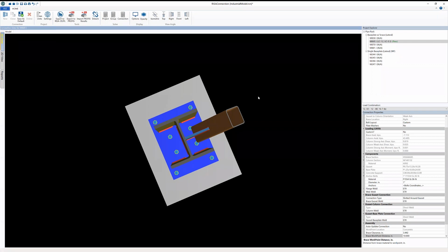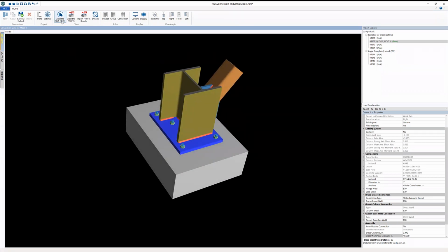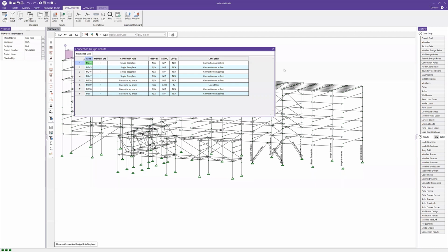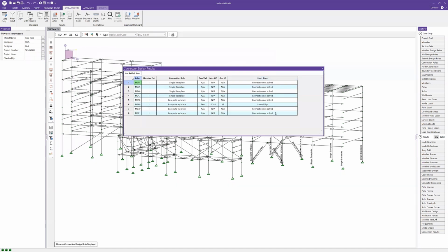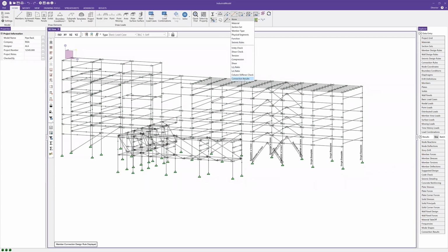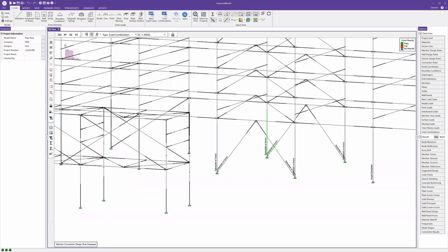With that, we can bring this model back into RISA 3D. Also, just to mention, this is one of the things that was new to the version earlier this year. We do have the ability to export to Profis, so you can connect with Hilti Profis to do the anchorage design, the concrete to anchor bolt design for all of those different anchors. In this case, I'm just going to go full circle and export back into RISA 3D. If we combine here, we can see I didn't solve all the connections, but we have some of the connections that are finalized, and then we have that one connection. If we look at our connection results, we'll get that one connection result with our passing grade there.